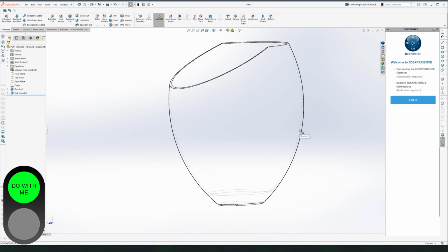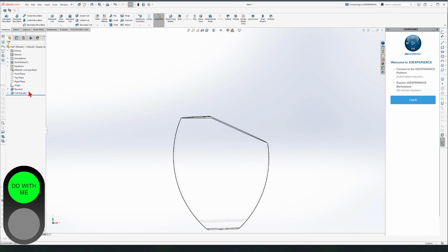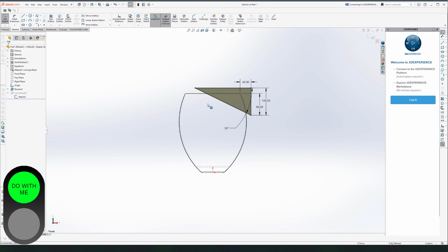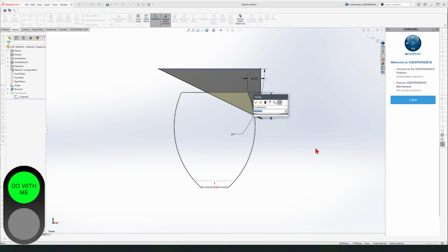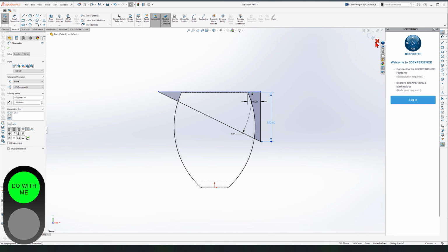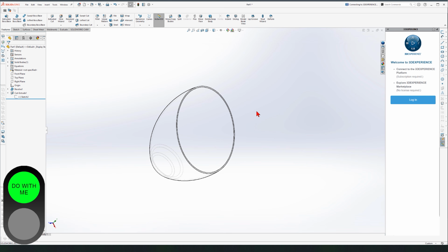But this time, we're not cutting all the way through because the second sketch was not set to go through the design. These things happen. Again, we are talking about the design intent at this point. If my design intent was to cut it in a way that it always goes through the vase, then I had to use a different set of dimensions and so on and so forth. But at this point, I think we can just try to come up with something like this and solve this issue. Like that. Anyways, this was the next item, a combination of Revolve and Extruded Cut.